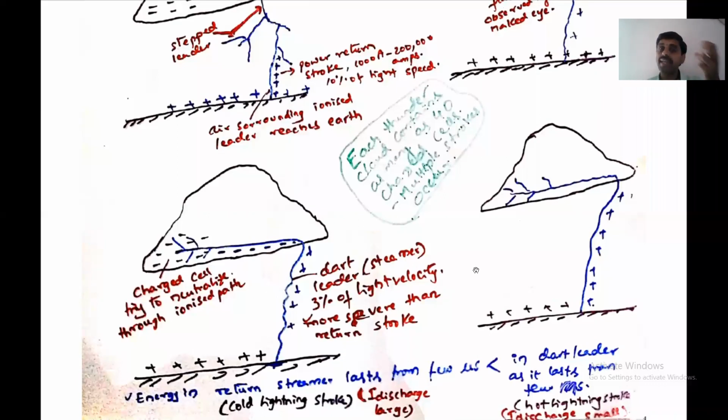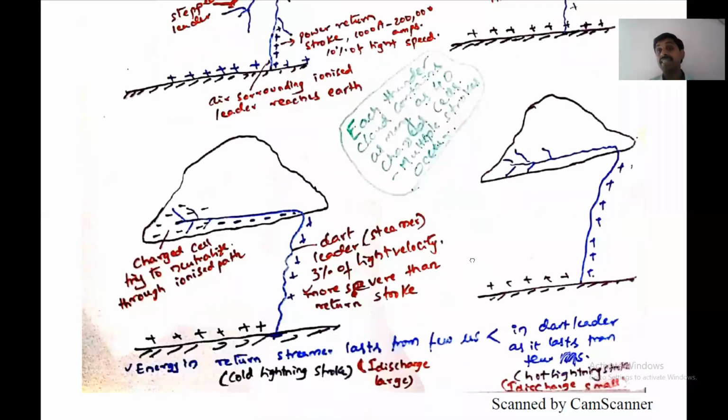Why can't we capture the energy in the lightning? Although the voltage associated with it is more and the current is more, it is lasting for only a few microseconds. Energy means time. You must have sufficient time to capture the energy. If you don't have sufficient time, you cannot utilize the energy. It has power, but energy is less because time is less. But its effect on the equipment is more. Let us see what that is.